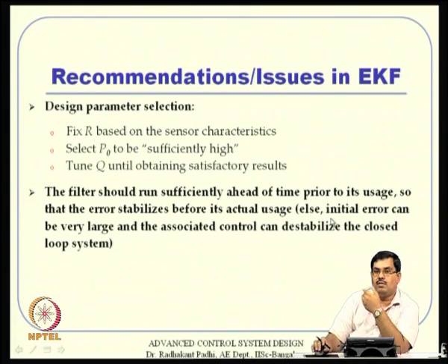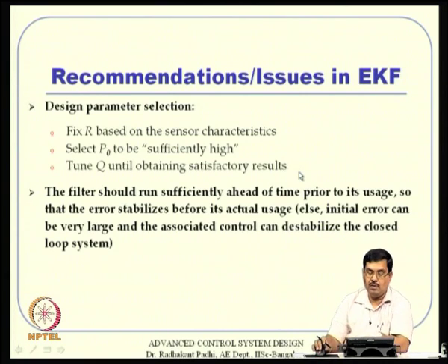So, especially when you want to close the loop, that means you want to use the estimated state in the control design and things like that. The recommendation is that you start operating your filter in the background for some time, and only after some time do you close the loop for the controller. By that time the error is stabilized and small, and it will operate as if it is the true state. So, invariably you will see that there is some sort of an initial time lag given to the filter to stabilize before its actual usage.